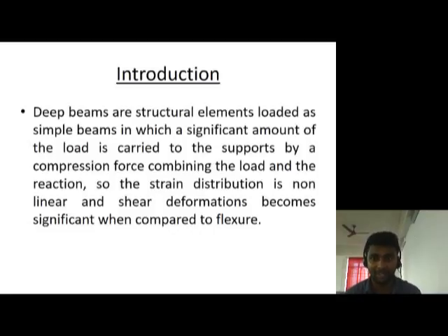Introduction: deep beams are structural elements loaded as a simple beam. They are related to simple beams in which a significant amount of the top load is carried to the support. The total load will be carried to the support by a compressive force combining the load and the reaction. So the strain distribution is non-linear and the shear deformation becomes significant when compared to the flexure.